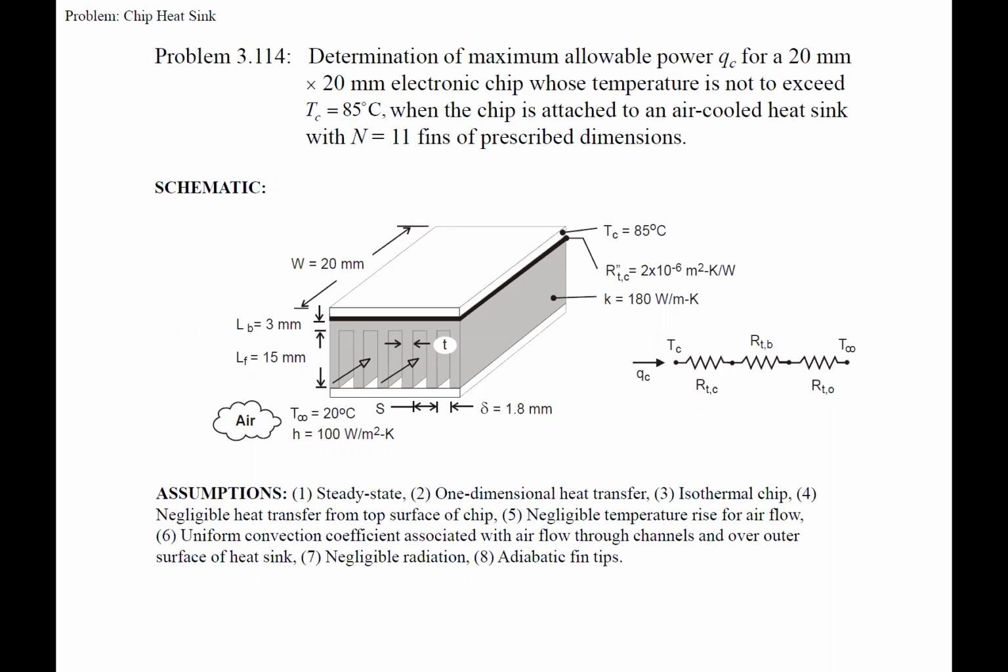An adiabatic fin tip condition may be assumed, and airflow along the outer surface of the heatsink may be assumed to provide a convection coefficient equivalent to that associated with airflow through the channels. And then part B is just more of an exploratory part of the problem.